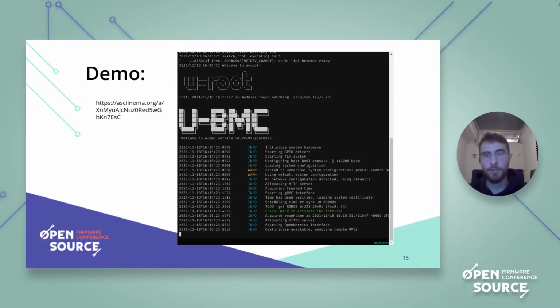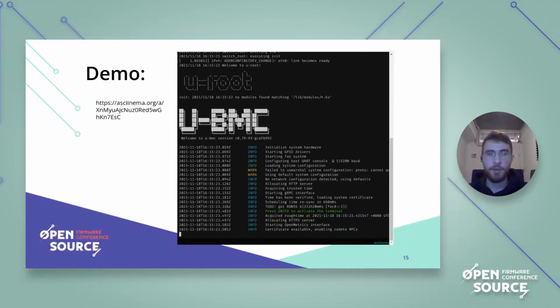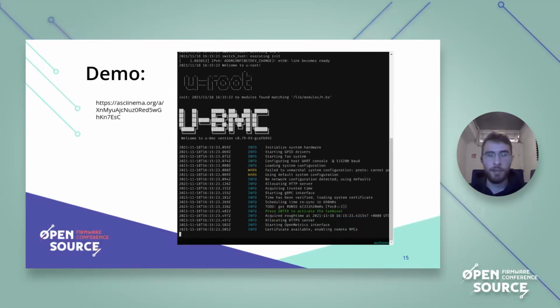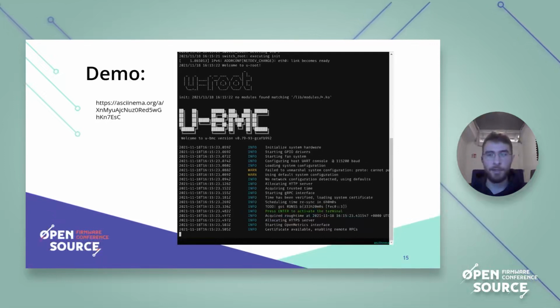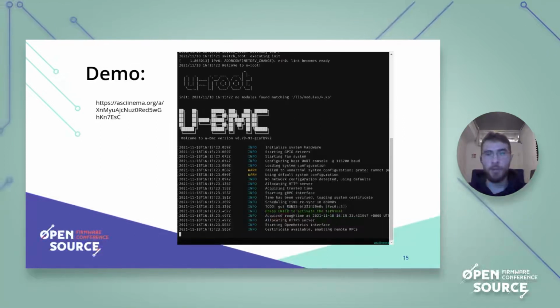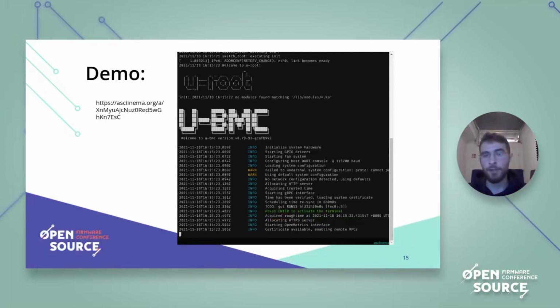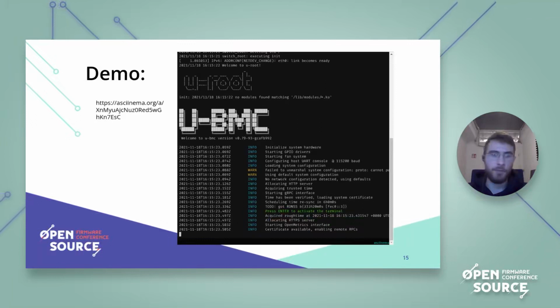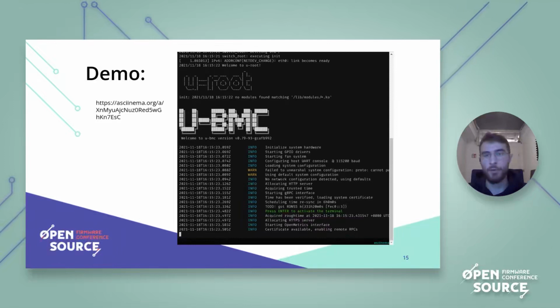trusted time. Therefore, if trusted time cannot be achieved, any communication to the outside will be halted until trusted time is achieved. So it will retry that several times, and if it is not able to get any way of trusted time, it will then just simply reboot itself and see if it can get that. Otherwise, the local communication via serial will always be online, because if you're at the machine physically present, then you can even trust the machine using, well, the wires to the machine, because that is already a trusted channel. You are at the machine and you're working with the right machine.